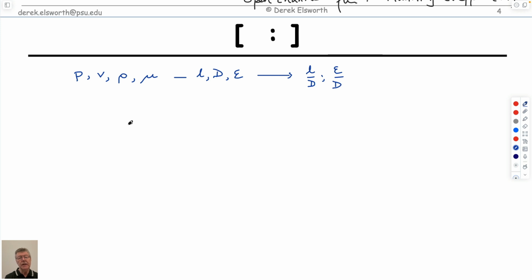And I'm going to say that let's take diameter, velocity and density. And so Buckingham Pi says that we can get non-dimensional parameters. So these would be what we call pi 1 and pi 2, 2 pi groups. This is going to be what we'll call pi 3, and I'm just going to do it by inspection.